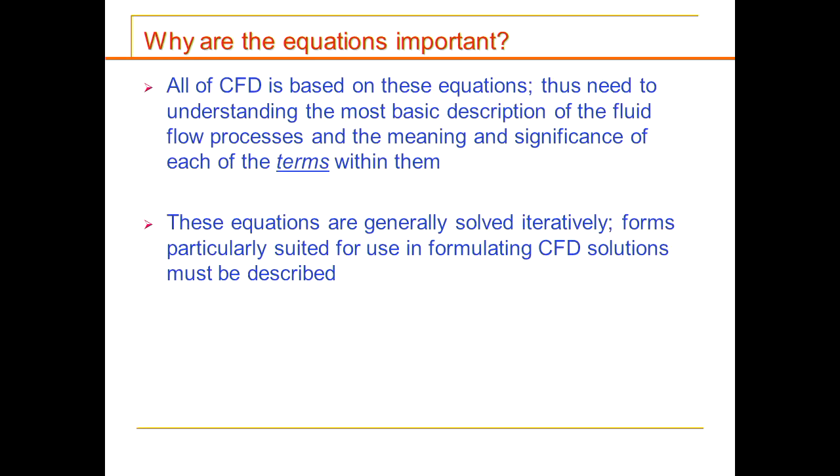If you are doing a transient solution, meaning that your result is time dependent, then your iterative process will go every time step, meaning that after the first time step, you will begin from the start, starting from a very high residue, and then you need to iterate for a certain number of iterations to achieve your next time step. But I will talk more about the transient simulation later.